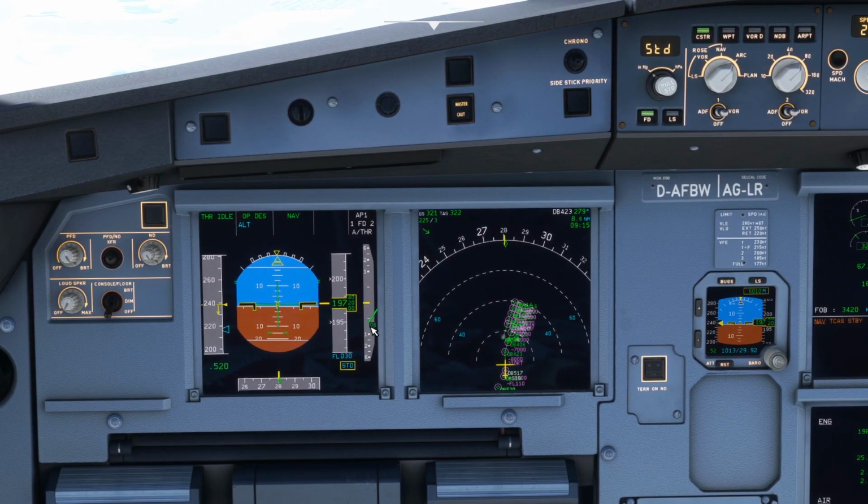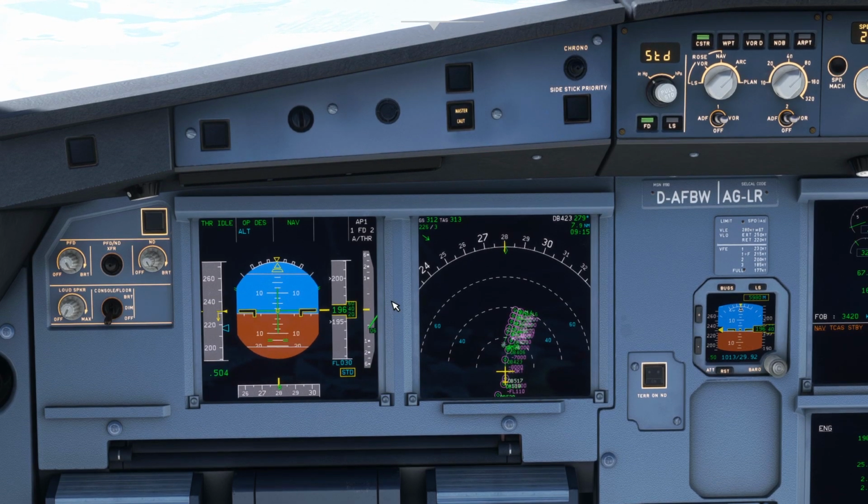Now, right now, vertical speed is 600 feet per minute. We should be descending at a higher rate because anyhow, once the speed is reduced, I can take the flaps. So you can see with the flaps, you have a speed limit of 230. Now, suddenly the vertical speed will increase, and I think now the vertical speed will be more than 3,000 feet per minute because we're going at a slow speed. So at a slow speed, the plane can